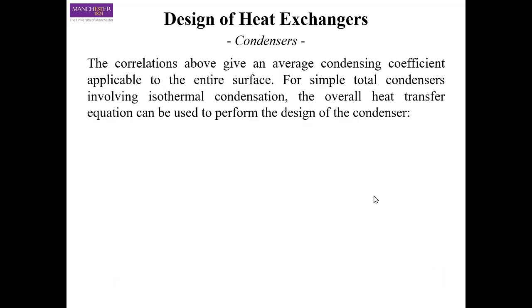Okay, so the expression that we developed for Hc in the previous slide gives you an average value of the heat transfer coefficient of condensation for the entire surface. And if you remember, when we were doing the analysis, we considered that the whole bundle is involved in the heat transfer, and as such, we have the entire surface in the system.